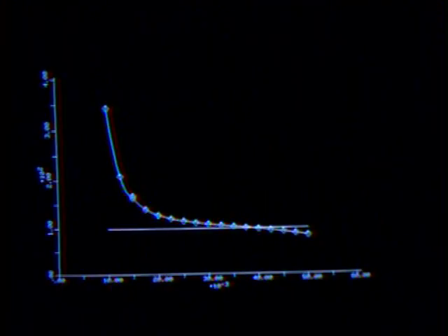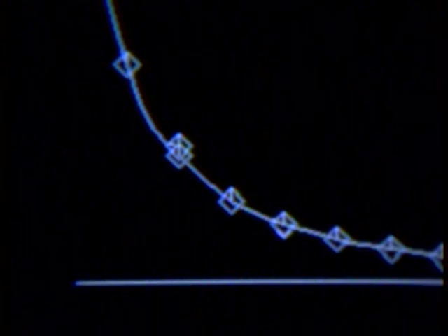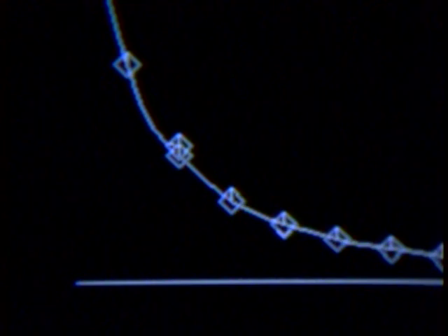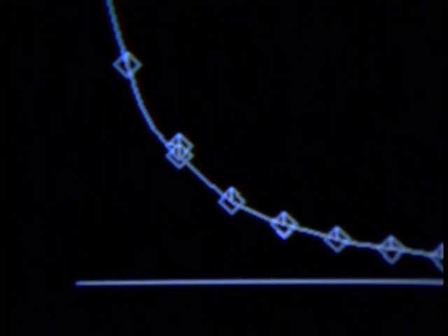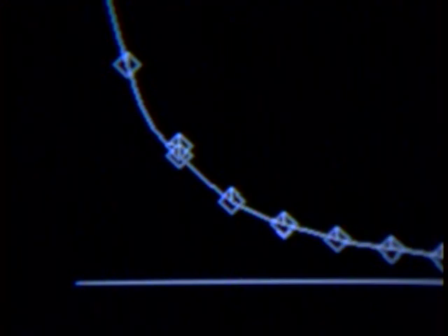Note that the stress predictions at the nodes, when calculated for the different elements, are almost the same. Only at one node can we actually see a difference, and it is quite small. Note that two elements couple into this node. Hence, there are only small stress jumps along the horizontal symmetry axis of the plate.